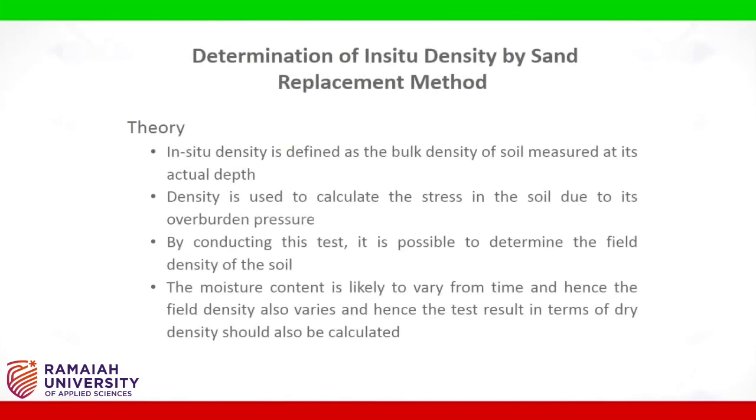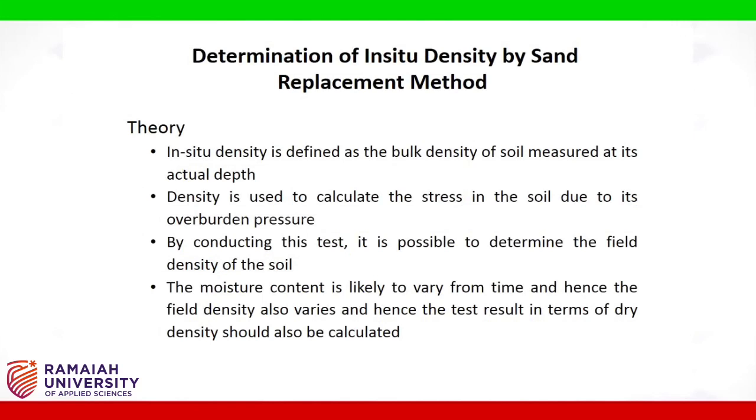In situ density is defined as the bulk density of soil measured at its actual depth. Density is used to calculate the stress in the soil due to its overburden pressure. By conducting this test, it is possible to determine the field density of the soil. The moisture content is likely to vary from time to time, and hence the field density also varies, and hence the test result in terms of dry density should also be calculated.